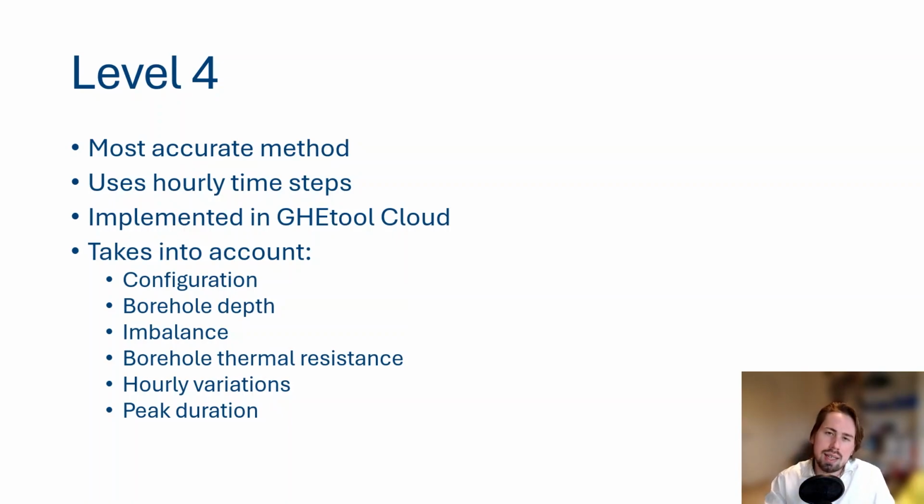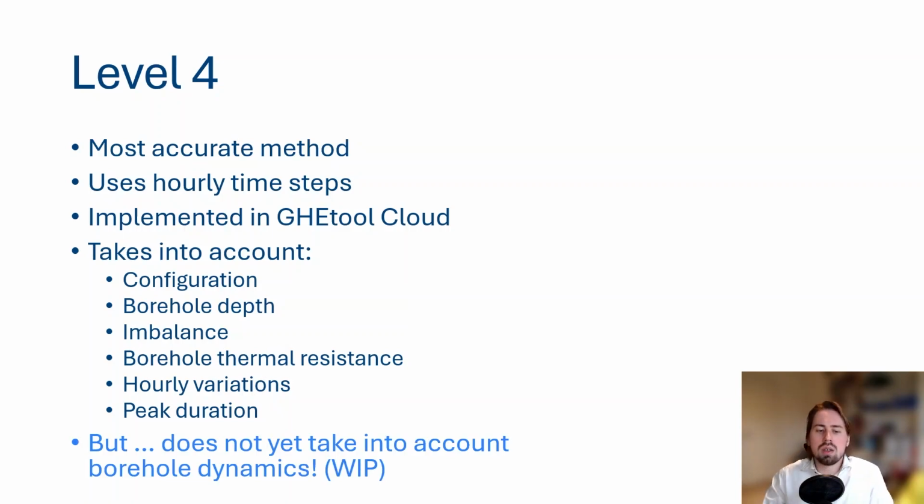But even so, it can be enhanced, because we do not yet take into account the borehole dynamics. If you recall our discussion on the short-term effects, where we talked about the borehole thermal resistance, if you do not recall that, it's linked in the description, we said there that it's a steady state model. So we assume that all the energy exchange is immediately coming from the ground, and the thermal inertia of our fluids and our ground is not taken into account explicitly. We're now working together with the University of Leuven to come up with newer models to actually take this into account and to make the level 4 even more accurate than it is today.